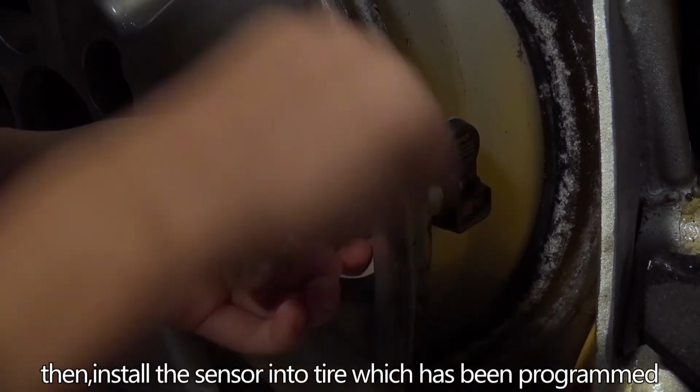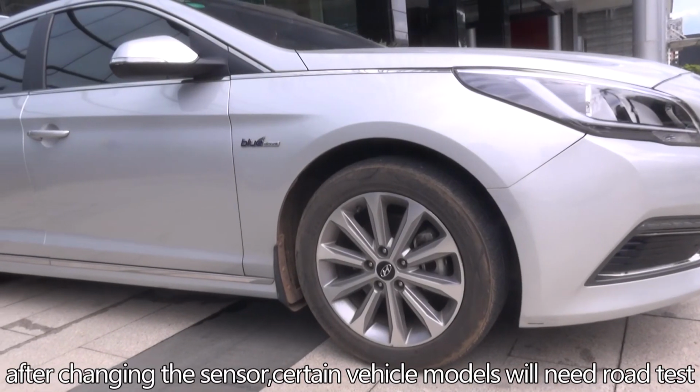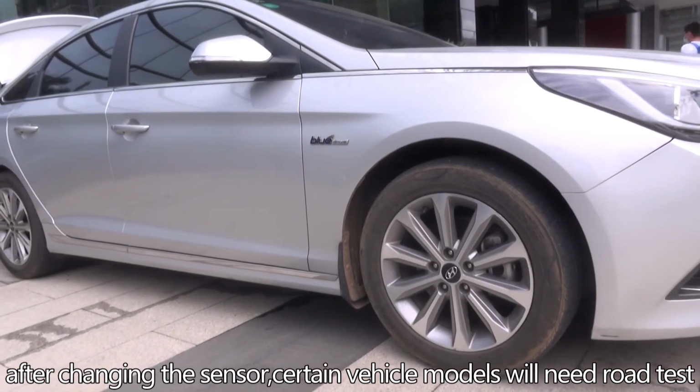Then, install the sensor into the tire which has been programmed. After changing the sensor, certain vehicle models will need a road test.